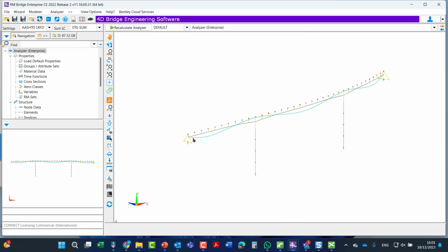Okay, so we also have a prestressing tendon that goes through the bridge, and that should be taken into account for the ultimate capacity, because the prestressing steel is not at its limit when we place it. So that means that it can be used as an active reinforcement, I would say, with some reserves in the stress domain that can be activated for giving the ultimate capacity.